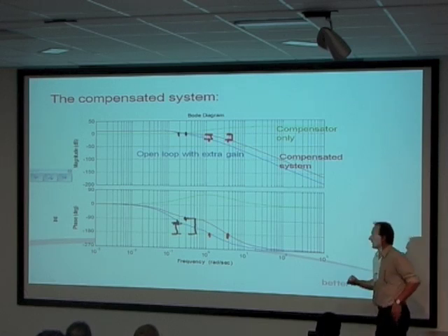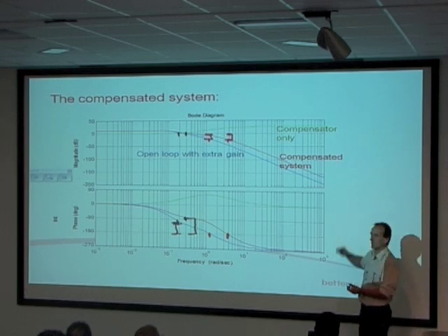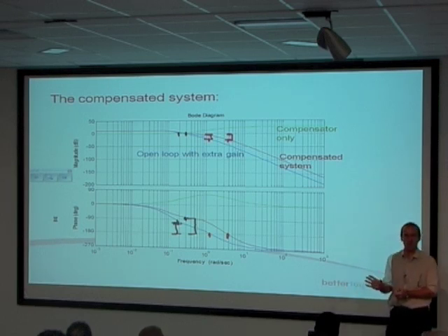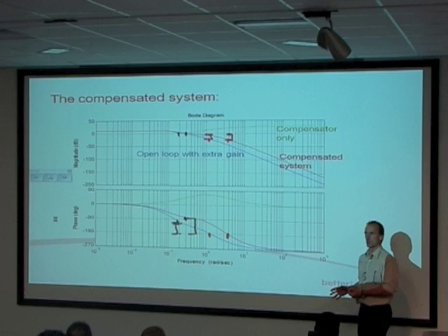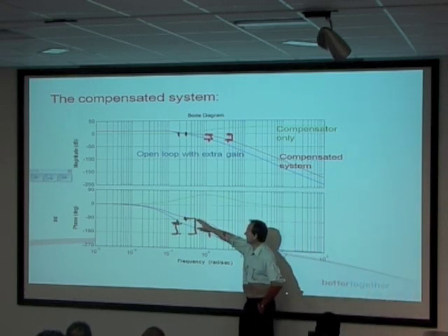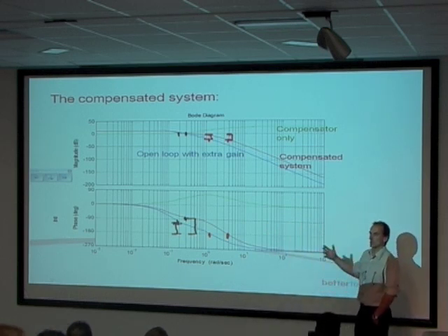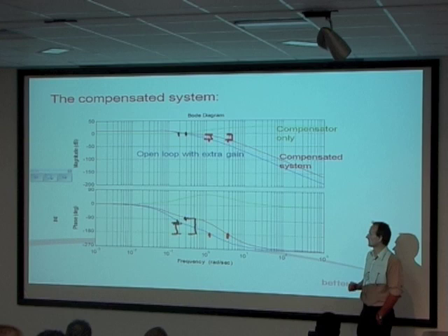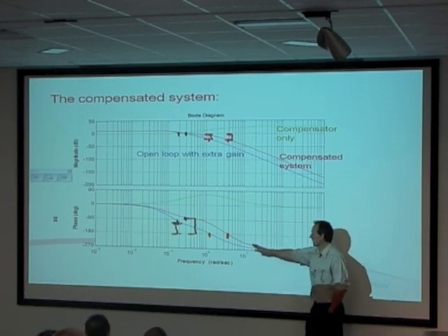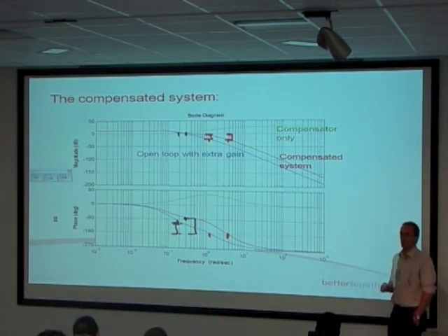Okay, so all of these things are to do with compromise. The fact that we're putting in more gain, generally speaking, isn't such a good thing for stability in a closed loop. But the fact that we can fill in this big lump of phase lead, I can use that to compensate for it. Then after a while, of course, when the effect of the lead goes away, my two curves are matching again.